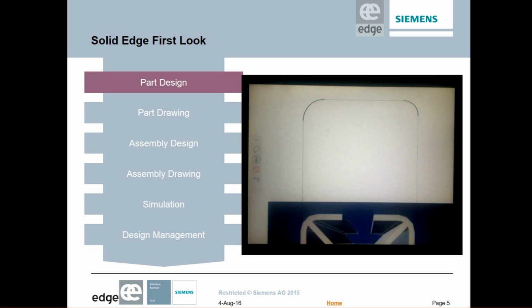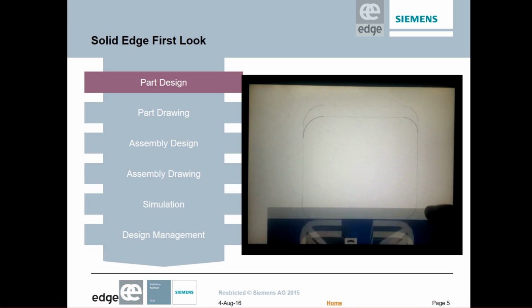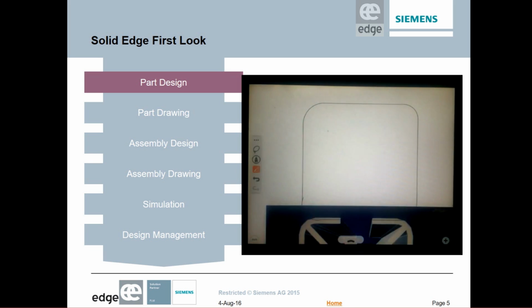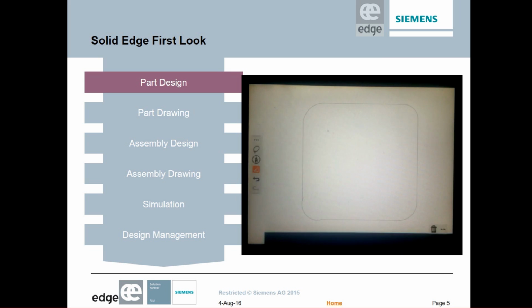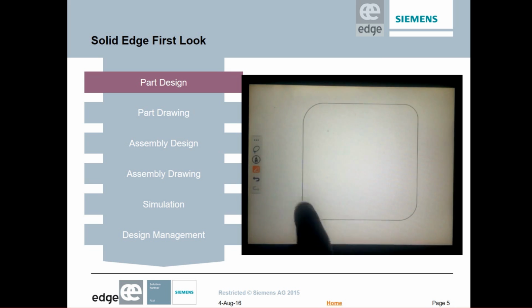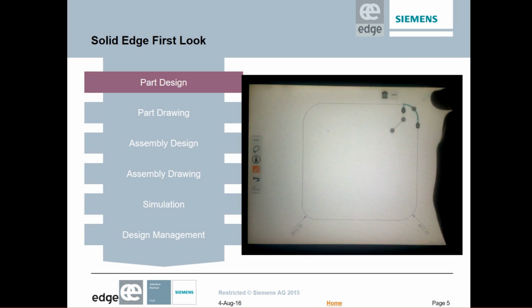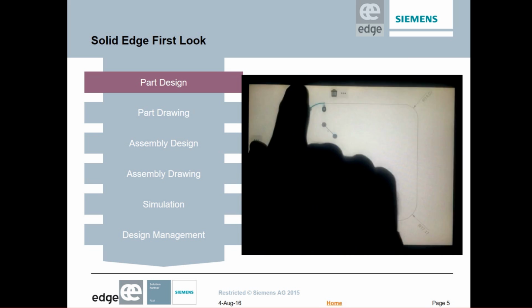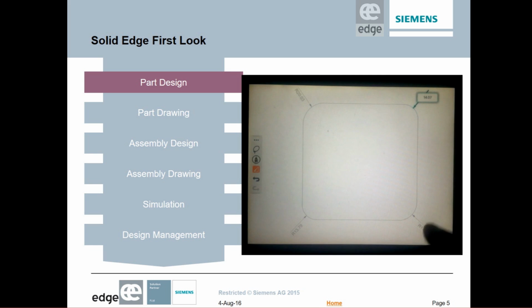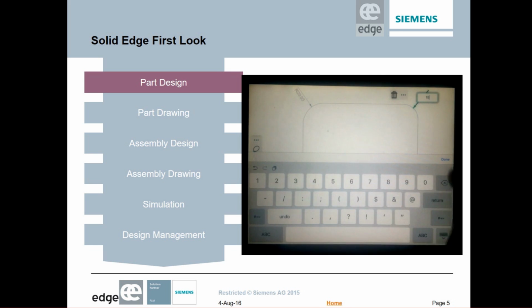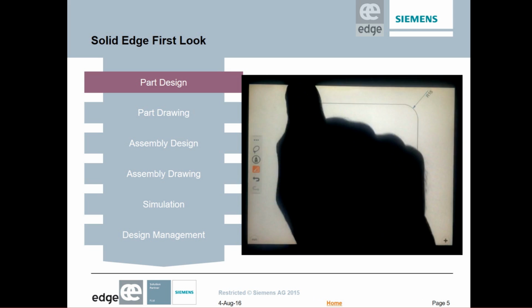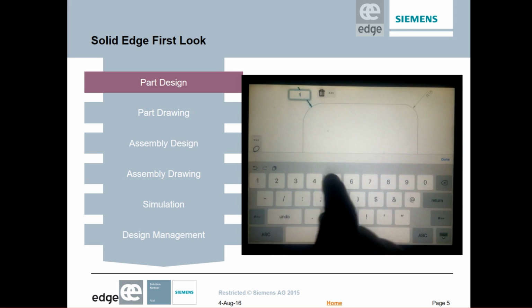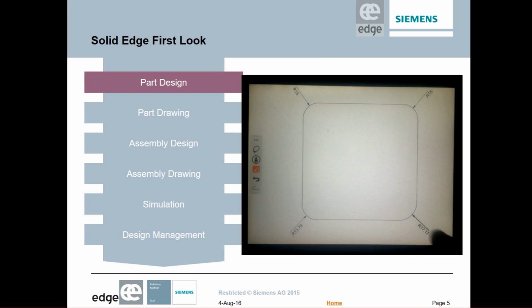Oops, you see I've left those grouped. I just want to ungroup and move the drawing down a little bit more. I just need to delete that edge, and whoops, I deleted the photo as well. I can put that back in, and I'll tap on the edge, and you see, simply by tapping I can show the key dimensions. By double tapping I can edit those same dimensions. So I've got quite a high level of control over the sketches on this iOS device.